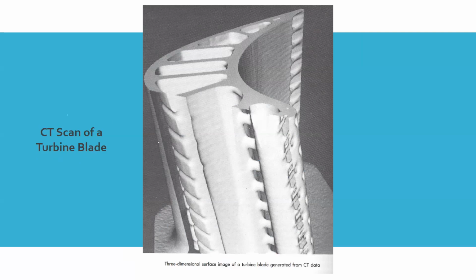Just from an economic side of it, a basic 2D X-ray system to do something like a blade, you're talking probably about in the $120,000 range to get your X-ray source and detector and computers to drive it. To get into a 3D CT scan type thing, you're talking probably $500,000 to $1 million.